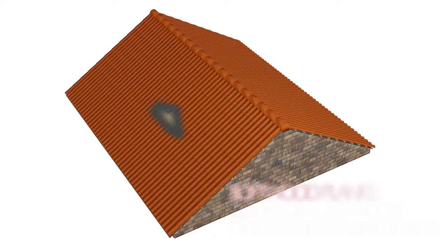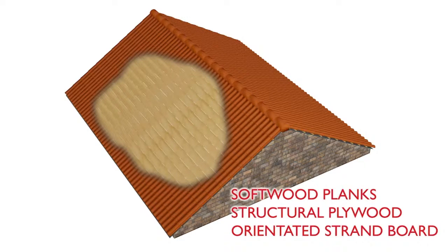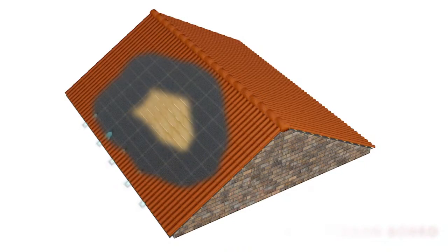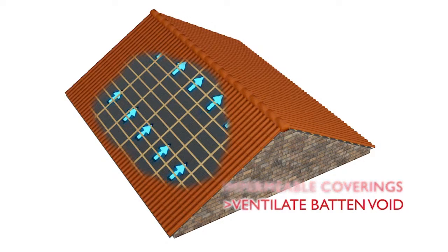In some specific situations, such as where wind loads may be particularly high or where traditional Scottish slating practice is being used, there may be sarking materials present on the roof. In such cases, it's always a good idea to check what effect the specific sarking type has on the ventilation requirements for that roof, particularly if reduced or no ventilation is proposed. If ventilation is required, this typically consists of a ventilated batten and counter batten space directly under the outer covering. This is a separate consideration from ventilation of, for example, the loft space, although if the loft space is ventilated, it's usually not necessary to ventilate the batten space too.